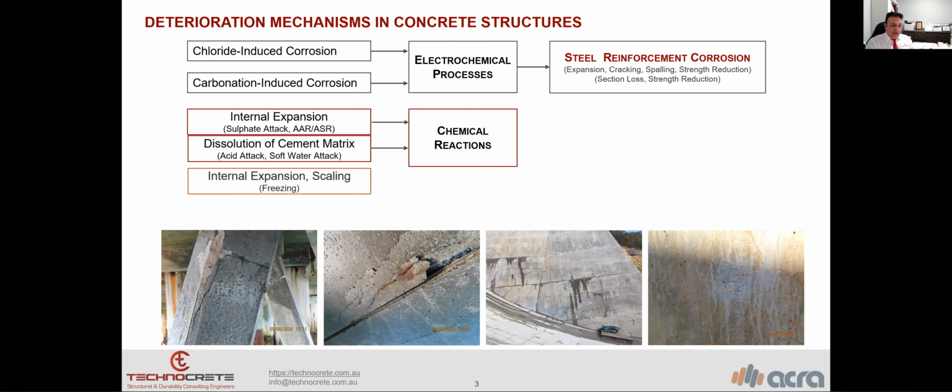And we may have physical deterioration, like freezing, or mechanical deterioration, like abrasion, natural sandblasting, waves, and debris. Natural sandblasting means if the structures are close to the coastal area in windy times, we have sands facing the structure and blasting it. Both of them are categorized as physical processes.